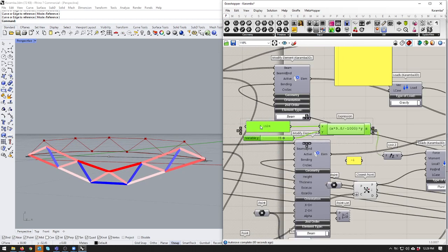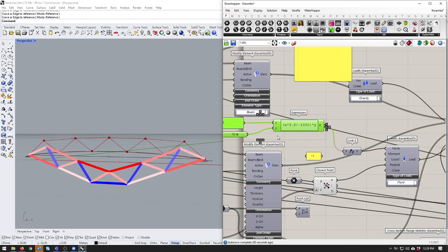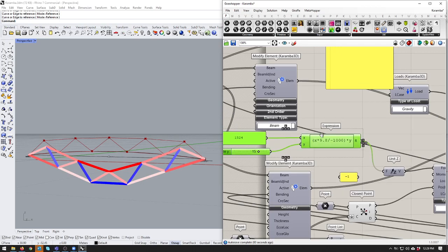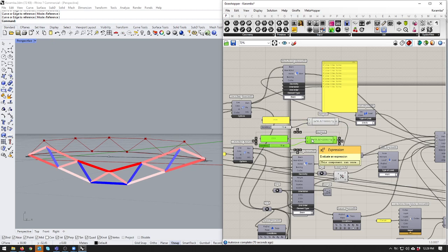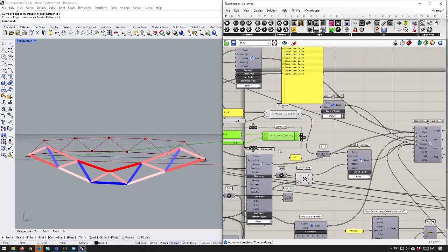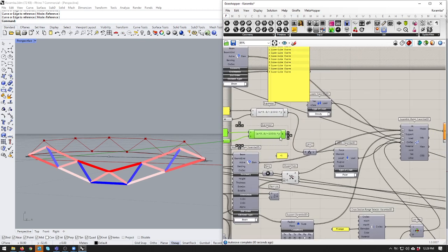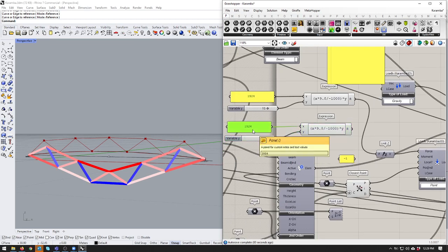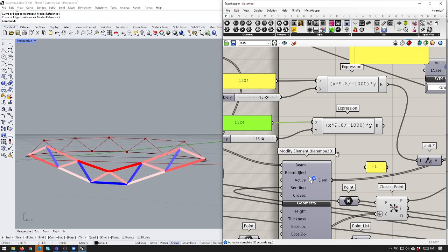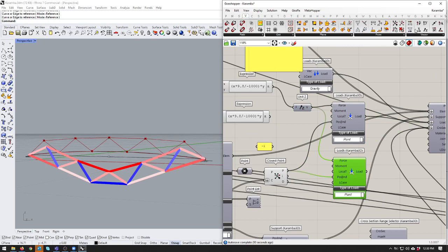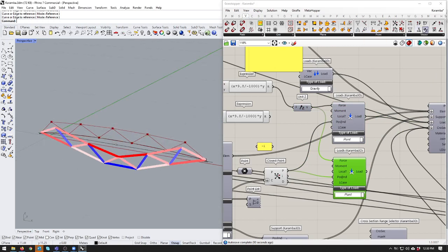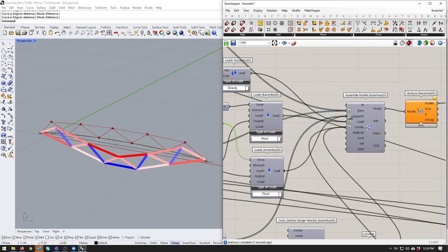There's going to be a whole different bunch of ways that you guys can work out live loads here. One thing I also implore you to do is with your structures, don't forget that live loads can be coming from different axes. It's not always just gravity. We have wind loads that can lift roofs up or push structures over. So if a car was to effectively crash into the side of this thing, then we can create a load for that as well. We just change the direction of it, so we throw in y. Now it's not really our job to work out whether or not these things are going to survive a crash, but